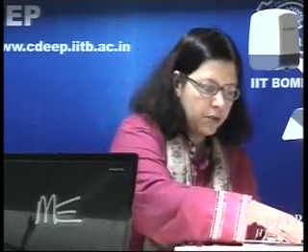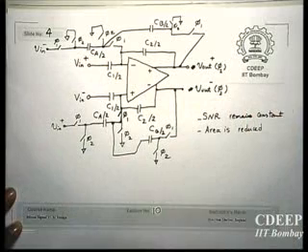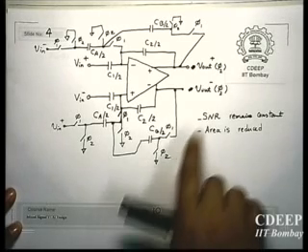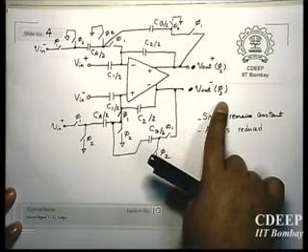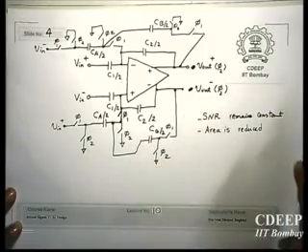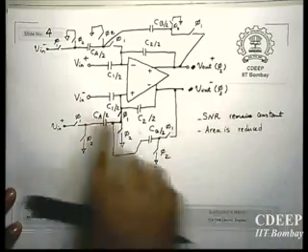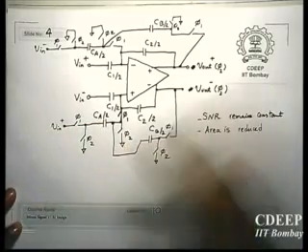Suppose you have a next stage, suppose this is a cascade of biquads, this is a biquad with order 1. Now if you connect it to the next circuit and the next circuit is working in phi 1, then you will have a continuous connection of all switches in the path, which will increase the series resistance of the charging capacitor. Therefore, if you want to sample it in phi 1, make sure that the next one, for example, suppose you have a similar architecture as the next stage.